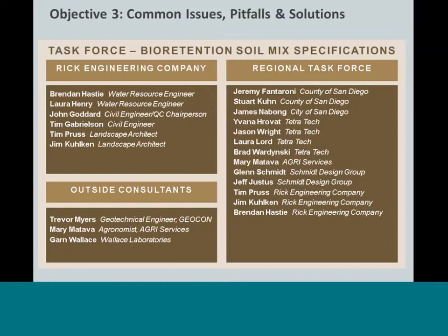A lot of questions were coming up on the material, and after things were constructed, we had surface ponding for days and a lot of issues from compaction. As soon as we started talking to contractors, we found that some of them were literally parking their bulldozers in the bottom of bioretention facilities at the end of the day, not realizing that we couldn't have compaction occurring in these facilities.